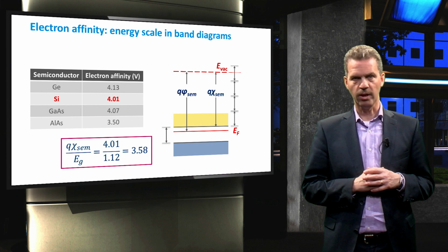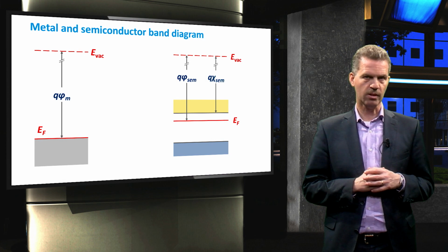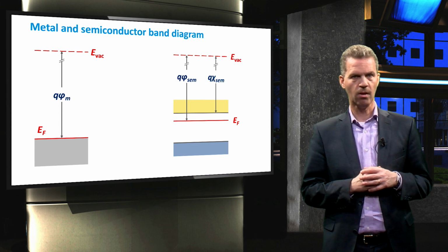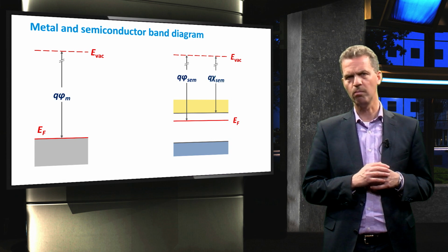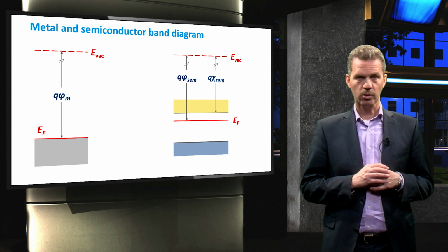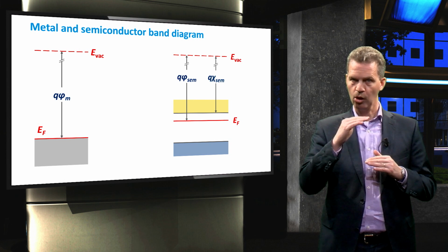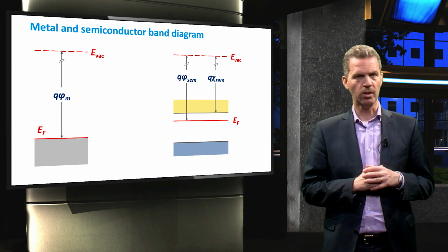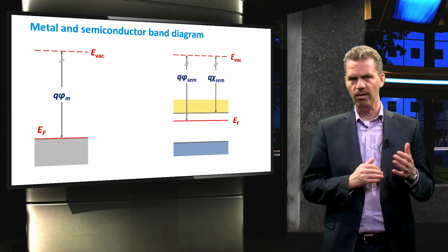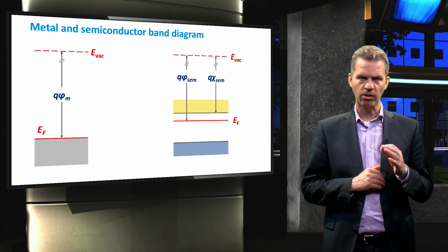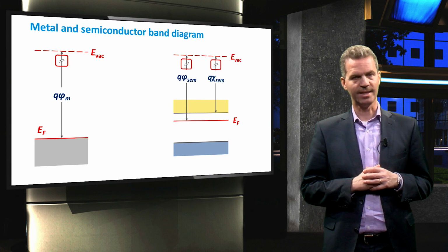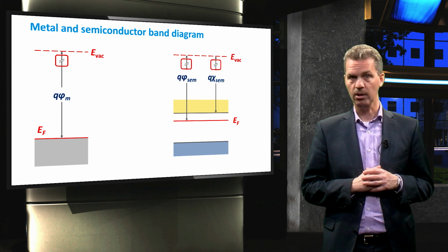Usually, when drawing a band diagram, we are more interested in the conduction and valence bands rather than the energy difference with the vacuum level, and therefore we put more emphasis on those energy levels. In order to include the vacuum level in the drawing, we tend to draw this level closer to the conduction band, which is not quite correct. However, we indicate this in the band diagram by drawing a cut indicating that this energy difference in reality should be larger.